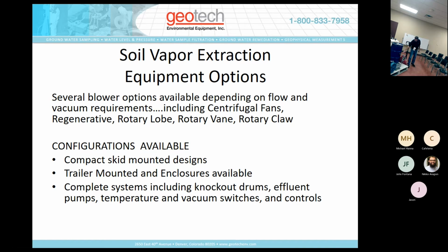There's also a high level switch in the drum. As the drum fills up, we don't want it to overfill and start sucking water into the blower. So we shut the system down then, and there's a manual drain here on the side.